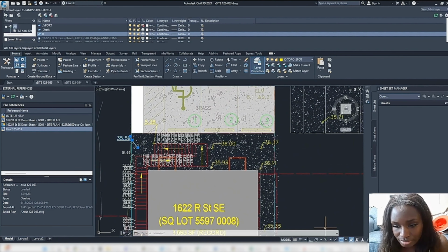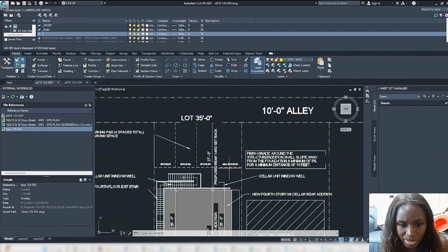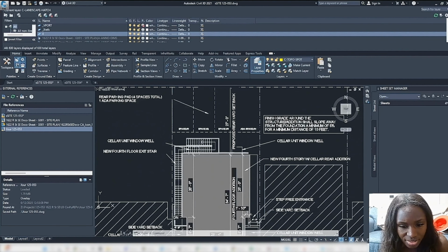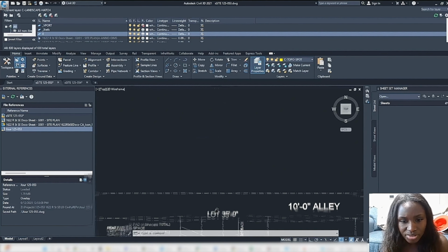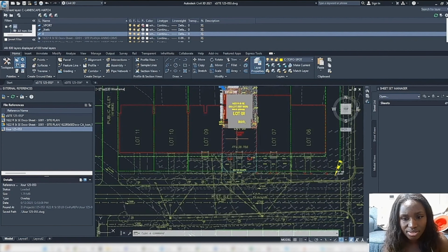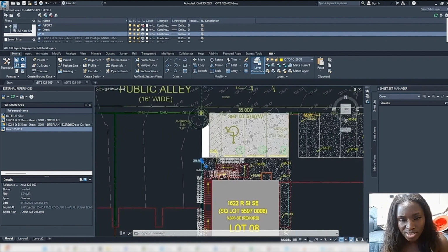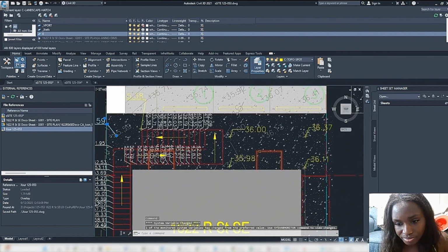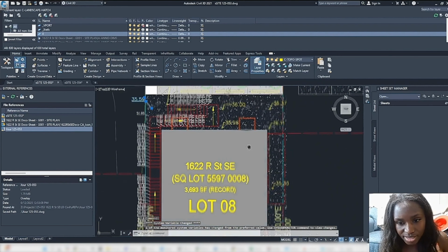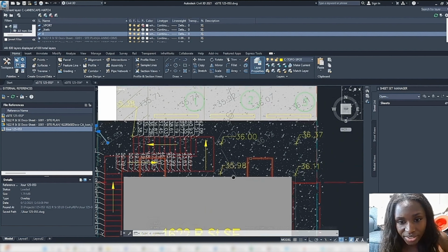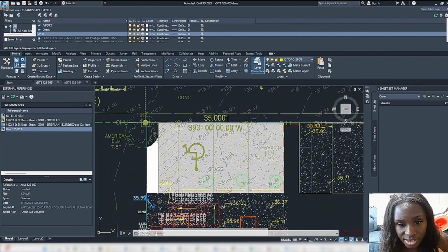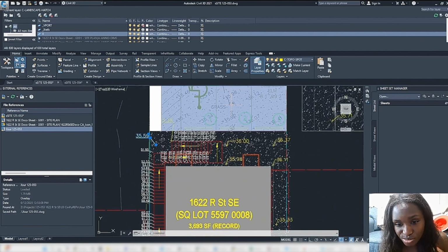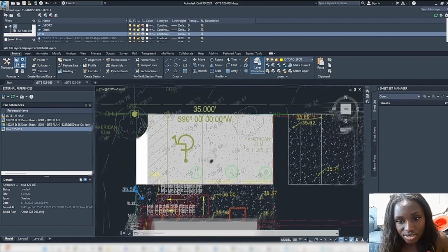Okay, so we just have to make sure that, and is there a door back here? Do you know? I guess there's no entrance from the back of the building. Okay, the only entrance is at the stair. So there's no direct entrance at the back of the building, but they have to walk around or go up the stairs to get inside. That also adds to how we design this, because if there was a door right here, and this is 36, and this is 37, we'd have to make sure that we can enter smoothly at that elevation.